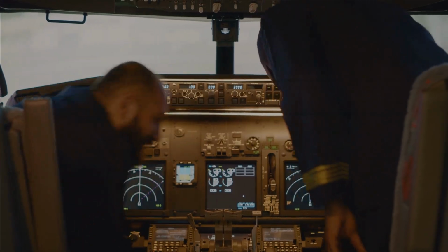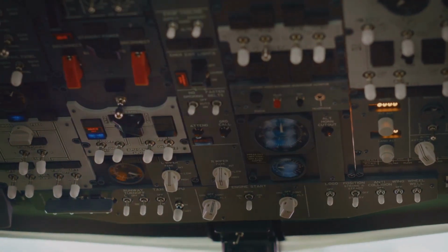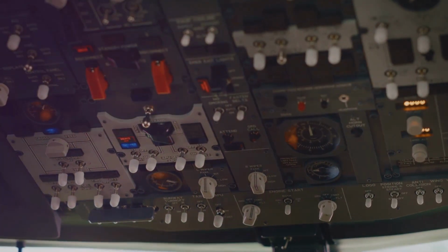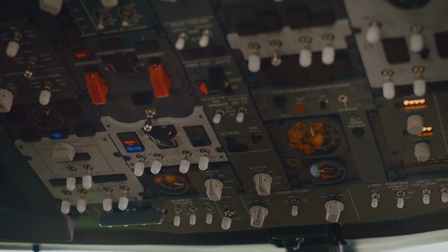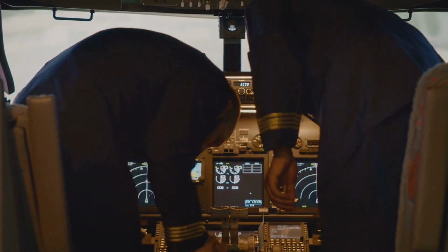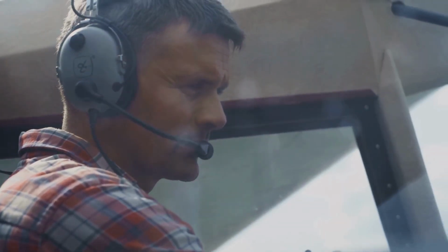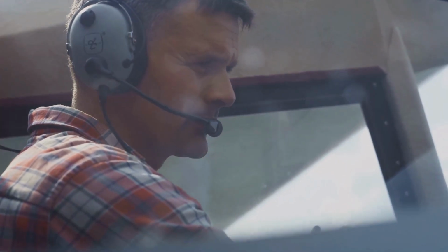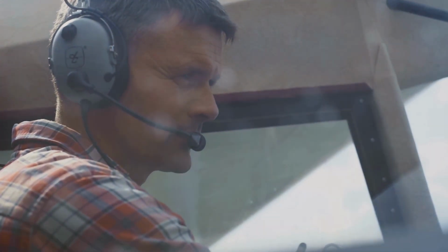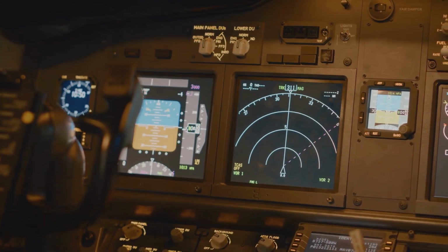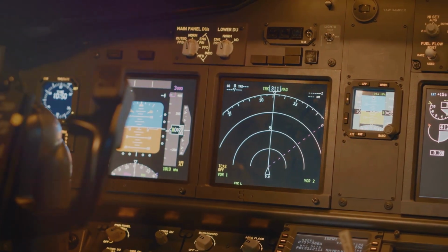So we've covered quite a lot about airplane speeds and performance. We've learned about the different speed indicators used in aviation, such as indicated airspeed, calibrated airspeed, equivalent airspeed, true airspeed, and ground speed. Each of these measurements has a specific purpose and is used under different flight conditions. We also discussed the standard speed symbols like VNE for never exceed speed, VNO for normal operational speed, and VA for maneuvering speed, among others. Understanding these symbols helps pilots operate their aircraft safely and efficiently.